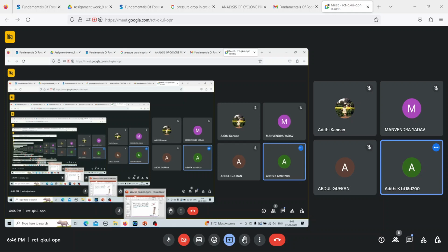So from this we get 10,000 into 9.81 divided by 0.12 by 4 pi square. And then you take a root of it, you will get n as 143.9 RPS. Now if you multiply that by 60, you will get it in RPM, which is 8,634 revolutions per minute. The answer is option D. So this is how you convert RCF into RPM.